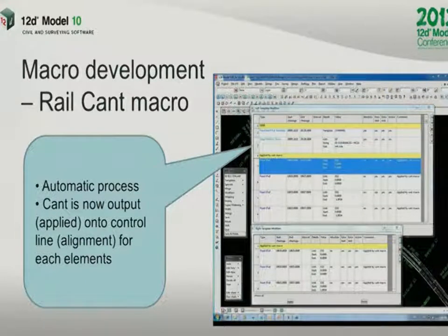It also allows us, especially for GCRT, Gold Coast Rapid Transit, this project, where the rail is embedded into a concrete track slab and connected to the roads, curbs, footpath, drainage features, etc., these CANT macros really enable close coordination with the road designer, track form designer, and drainage designer to ensure an accurate and detailed cross-section is produced at the end of the day. Of course, the advantage of the CANT macros, which I mentioned before, is that they really save us a lot of time and reduce a lot of human error, provided we have input everything correctly in the beginning.